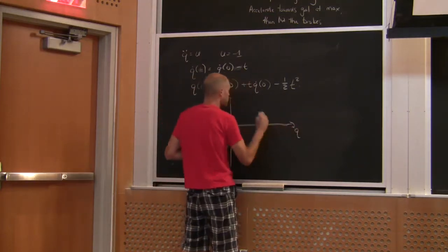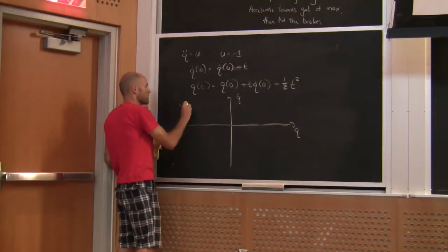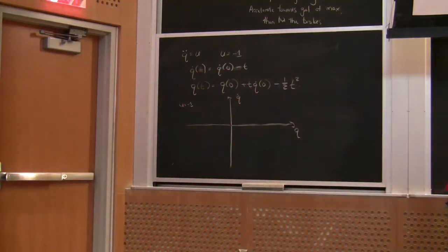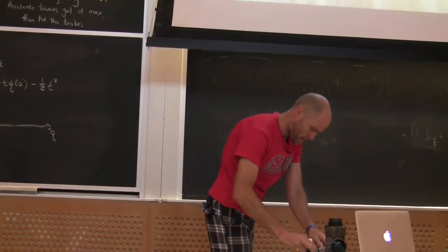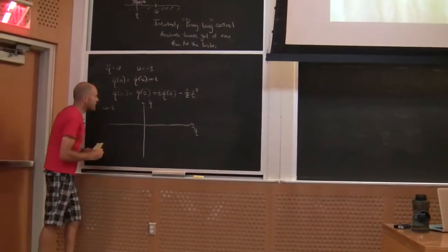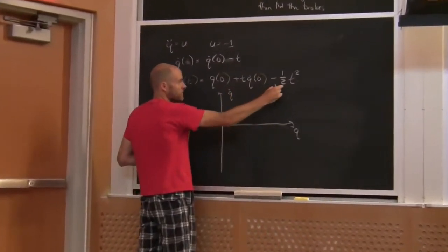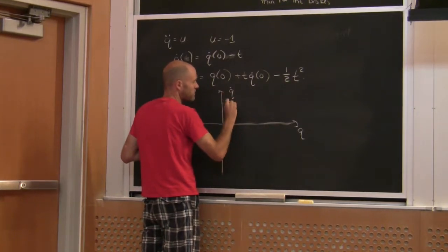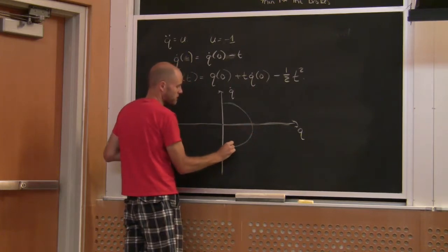So if I were to plot the phase diagram of us executing this u equals -1 controller in color, then I start here with some positive velocity. I'm going to continue, and then I'm going to start decreasing with time in position, and if you solve away for time, you'll see you get these trajectories that look like this, okay?